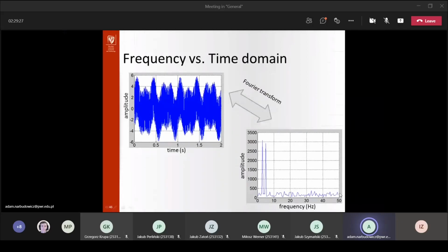Okay, so why is the noise here? The noise has much lower amplitude, and the difference between the signal amplitude and noise amplitude is seen as the signal to noise ratio that we spoke of earlier on. And of course, the white Gaussian noise, so-called, the basic model for noise, is considered to be frequency invariant, right? So you will see it all over, all your frequencies.